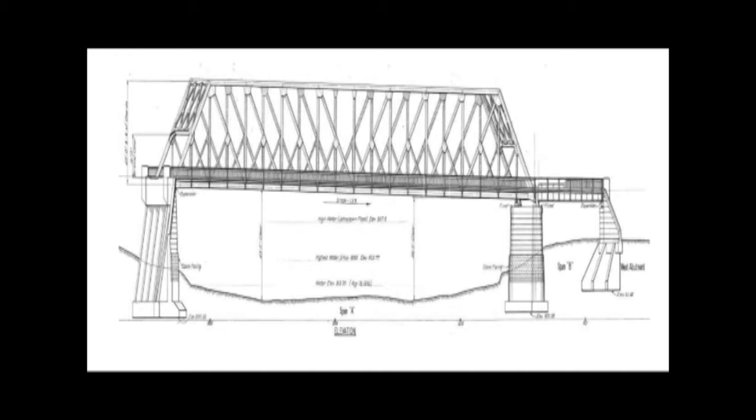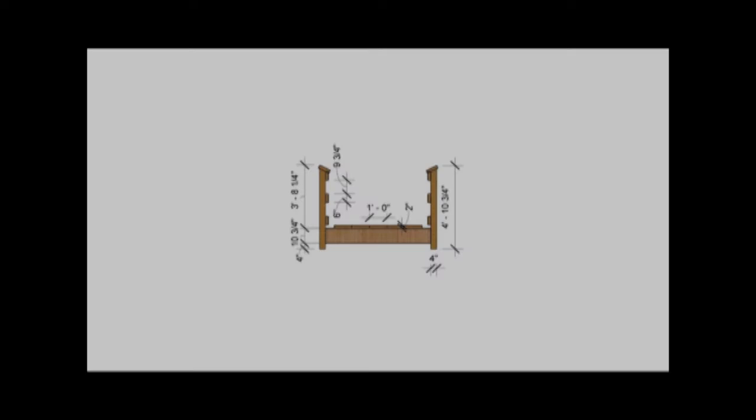That type of structure has a peculiarity also, so as to avoid the formation of whirlpools at the pier or at the central portion, so that the water may not form vortexes there. So the pier has its own significance and is designed in its own way, understanding the vulnerability of the cross section there, and the susceptibility of formation of whirlpools, vortexes, efflux, and so on.